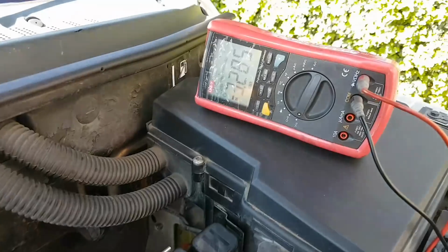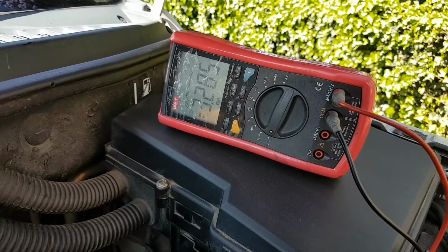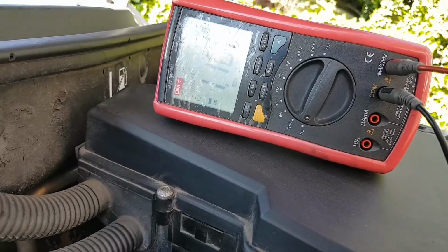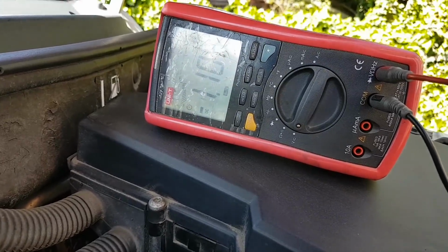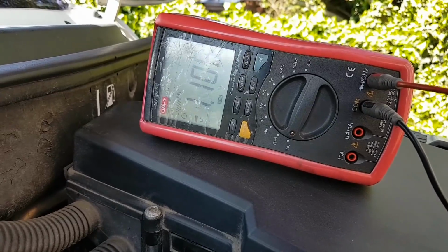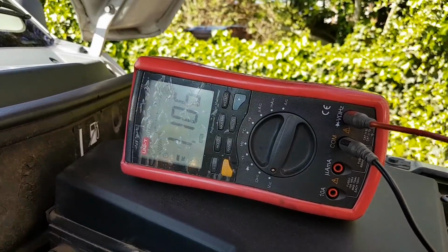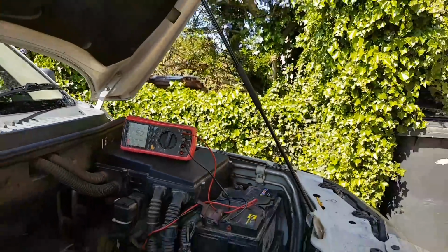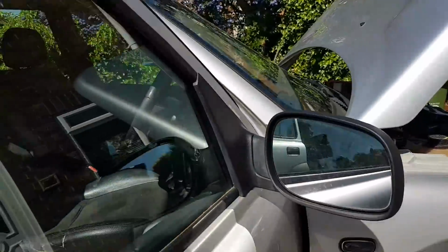With the engine idling, that voltage is showing minus because I have the probes the opposite way. The pump just went off, but with the engine running, that should be around 4.3 volts. That's the signal wire. And I'm going to show you when I start the engine, that doesn't go above 3 point something, 3.3.